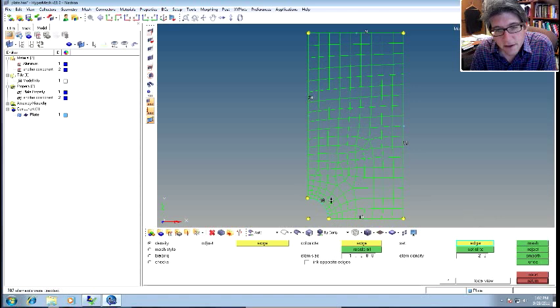I've got a more refined mesh here, and I'm going to get a stress concentration here. I don't need such a fine mesh out in the far field. And the elements look kind of nice. We can talk about checking the elements later on, but that's the way it goes. I think it's a good idea to fool around with these different ways of generating the meshes.